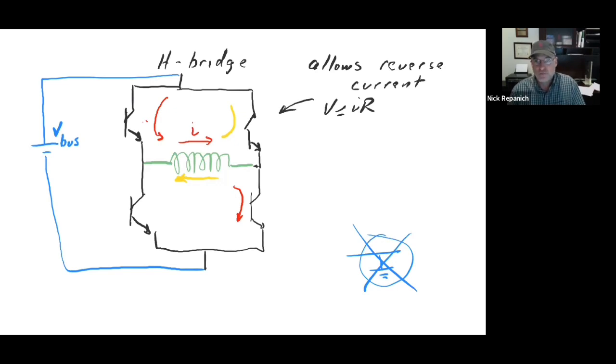You need a driver. You need something that can do pulse width modulation. And what that means is you need to be able to not just turn that on, we're going to turn it on and off and on and off and on and off. And we're going to count on the fact that the inductor is an energy storage device.